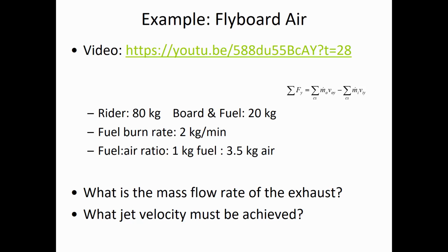And if the total mass is 100 kilograms, then the sum of the forces in the y direction to maintain level flight is going to have to be equal to 100 kilograms times a gravity of 9.81 meters per second squared.